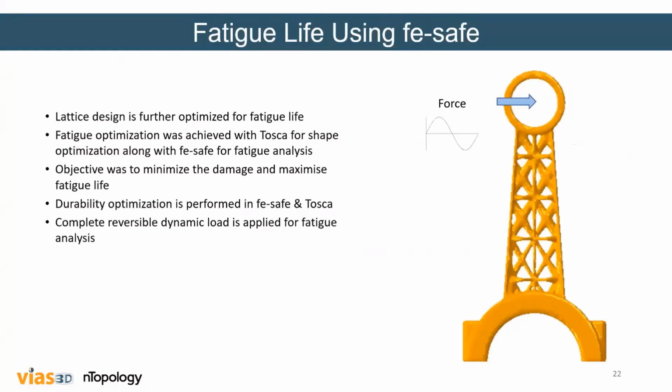So you look at the local distortions and how the stresses are, and because fatigue is a very localized phenomenon, there is always a concern that although you are structurally very sound in terms of your stress strain compared to your yield, maybe there are fatigue concerns in small spots where it can initiate a crack.